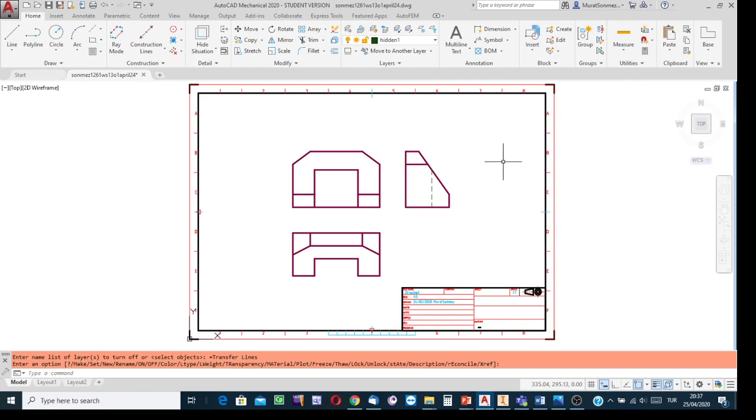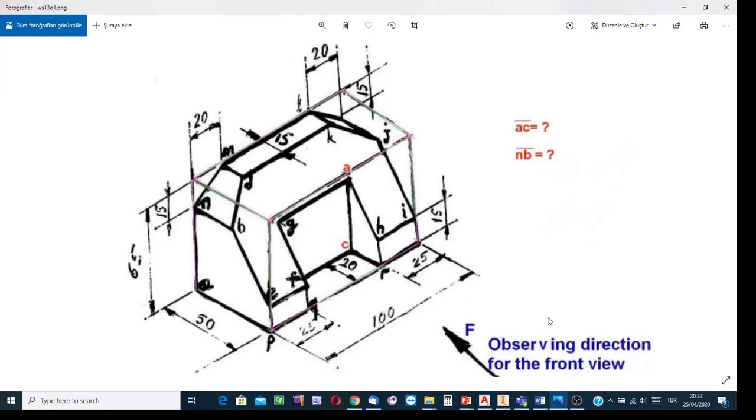But if you're going to use AutoCAD starting from the sketching stage for 3D model creation purposes, then there is no need to have such layers. Using the automatically activated layer, one of the layers, you can draw the necessary sketch and then apply the solid model creation process.